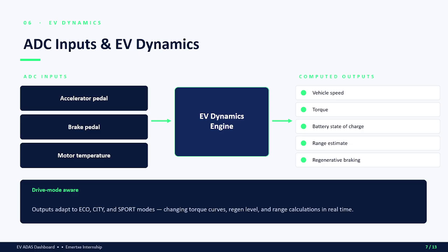ADC and EV dynamics. The ADC reads accelerator, brake, and motor temperature values. The EV Dynamics module uses these inputs to calculate vehicle speed, torque, battery state of charge, range, and regenerative braking based on the selected drive mode.